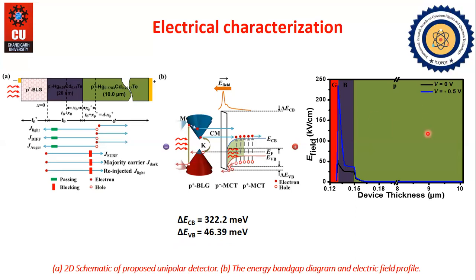We can see here the electric field profile at the different junctions, and it will increase with the applied bias voltage. The electric field is mainly distributed in the barrier layer, along the barrier layer, due to the existence of the high barrier resistance. It could be seen that there exists a high electric field at the graphene barrier interface, which is essential to quickly separate the photo-induced carriers, limiting carrier recombination and exhibiting quick response time.